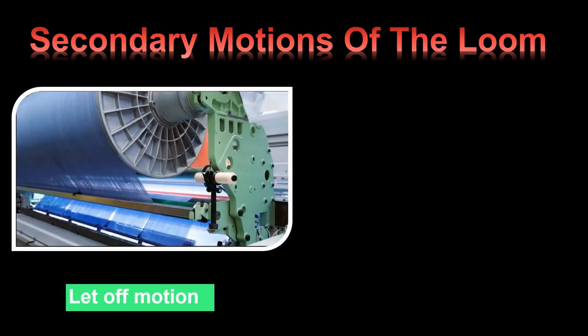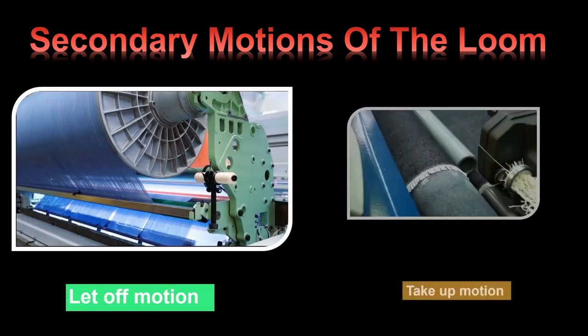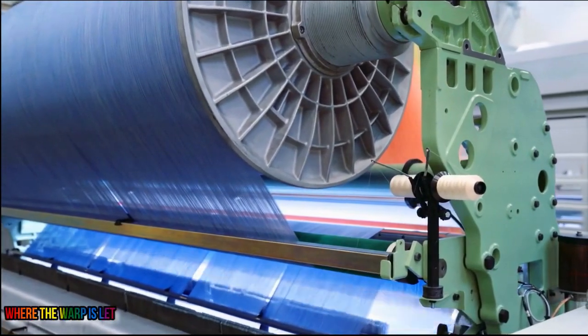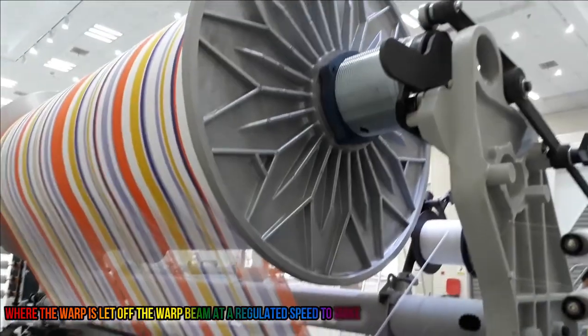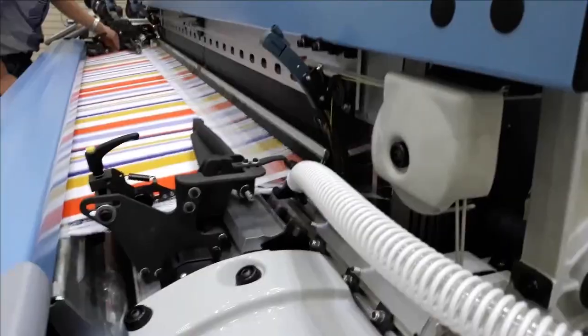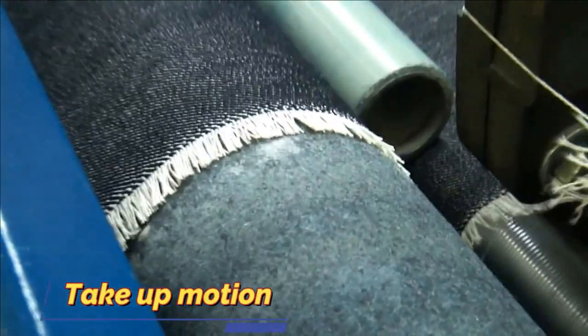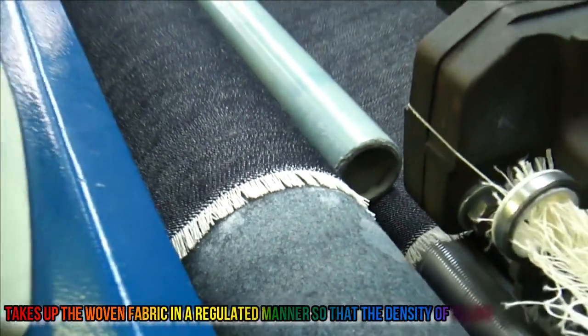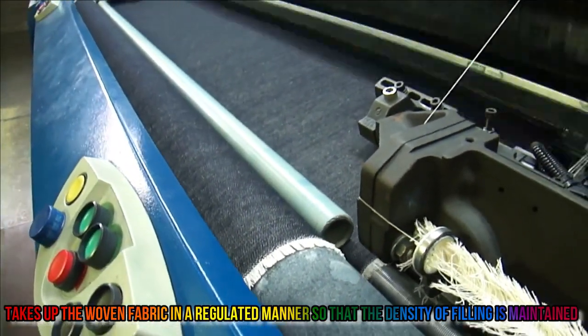The secondary motions of the loom are the let-off motion and take-up motion. Let-off motion, where the warp is let off the warp beam at a regulated speed to make the filling even and of the required design. Take-up motion takes up the woven fabric in a regulated manner so that the density of filling is maintained.